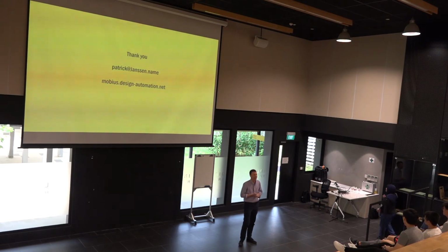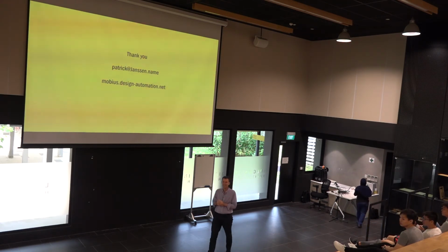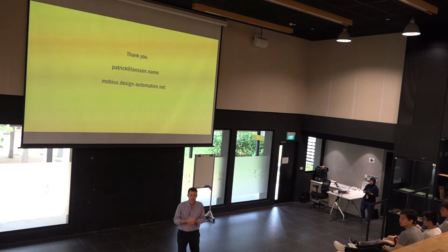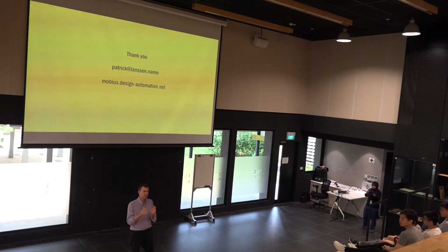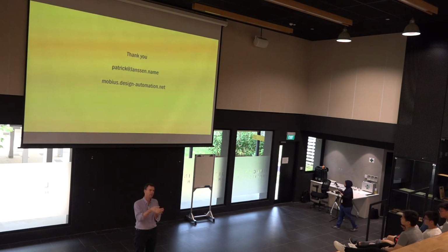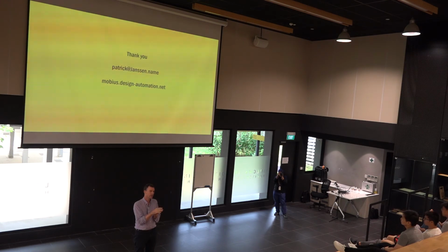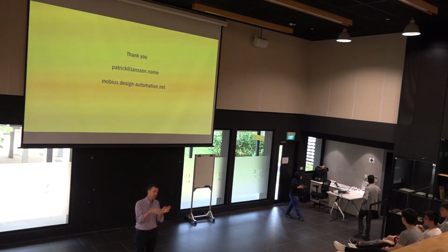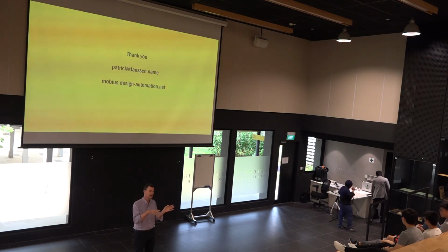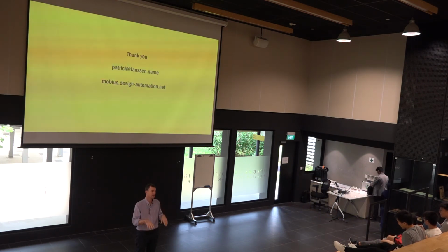How does the facade know the orientation? So for the orientation, you take the polygon and you measure the angle between north and the polygon's angle. I give it a range. So if it's between, you know, minus 10 and 10 degrees, then I say it's facing north.